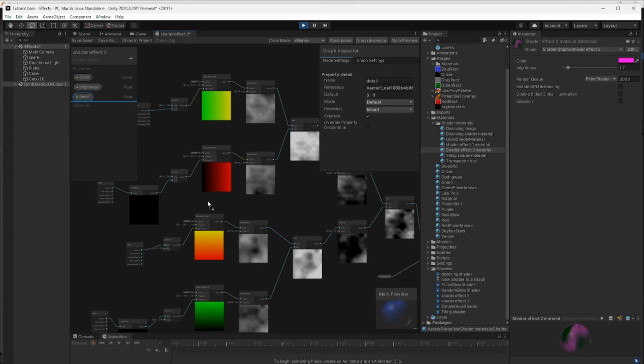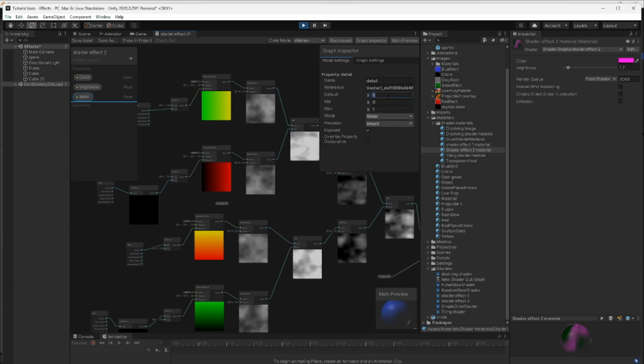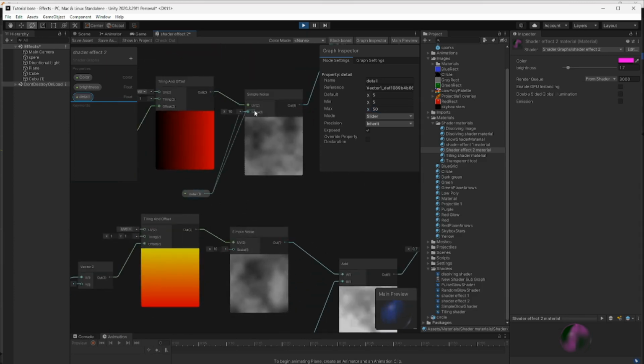Let's drag it right here. And let's give it a slider. Let's default it to 10 since that's what we were before. Let's go a minimum of 5 and a max of 50, just to see what that looks like. And we will connect that to every one of our scales.